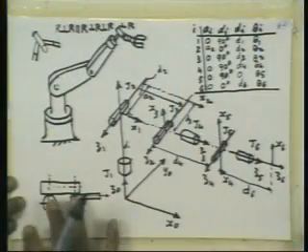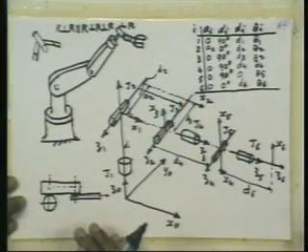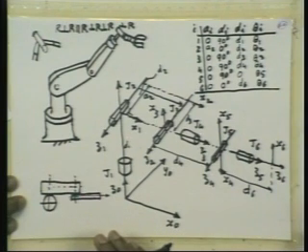And what does it mean physically? The 2 solutions and no solutions. Again, it's an issue of reachability. Only now we look at reachability in another plane. Earlier, if you remember, we looked at reachability in the x y plane of the global frame, right.